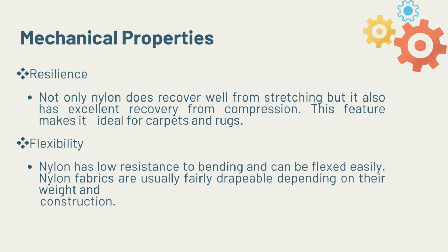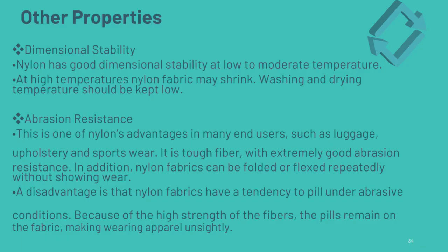Flexibility: nylon has low resistance to bending and can be flexed easily. Nylon fabrics are usually fairly drapable depending on their weight and construction. Dimensional stability: nylon has good dimensional stability at low to moderate temperature. At high temperatures, nylon fabric may shrink. Washing and drying temperature should be kept low.